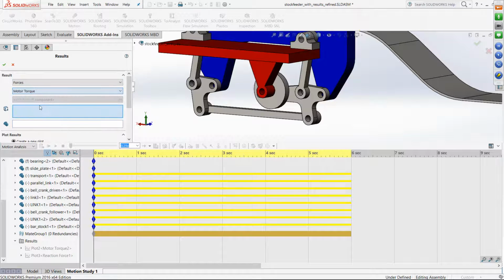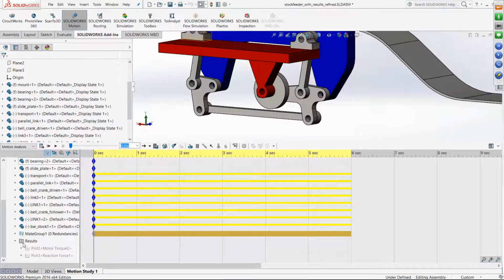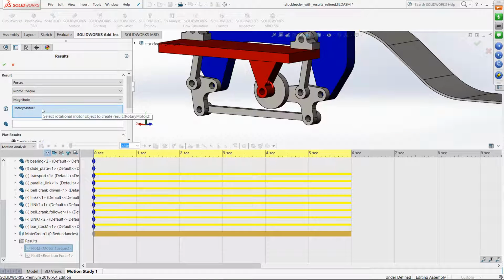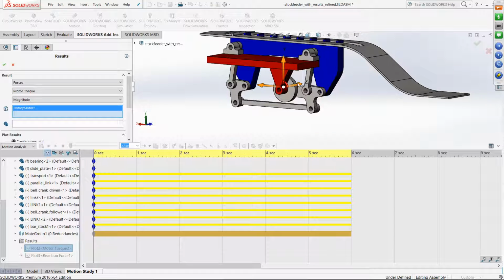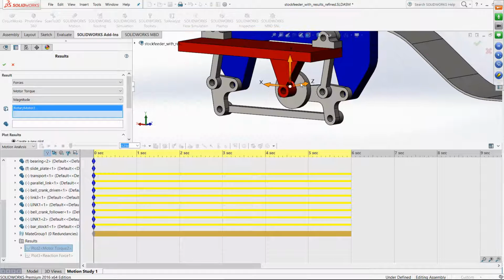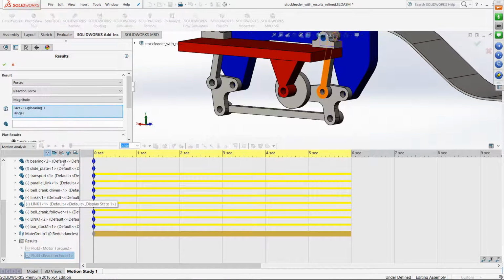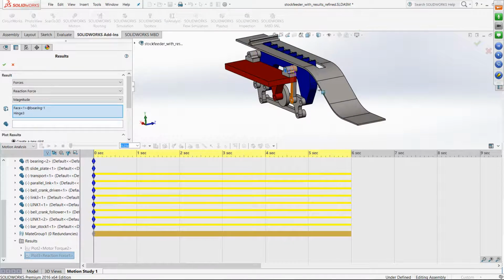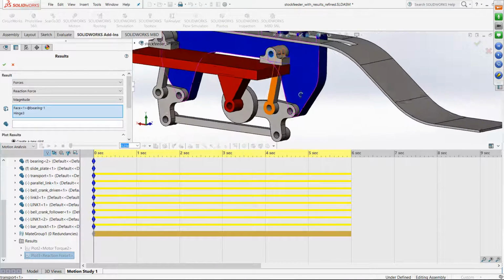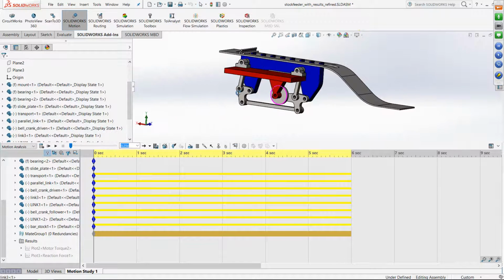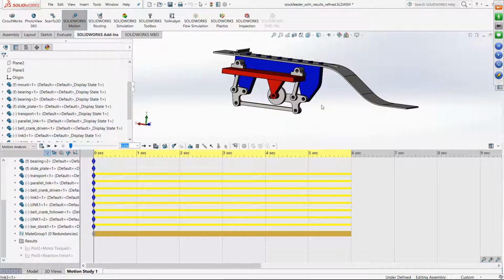I can select the motor torque, etc. So as I told you, this is not an animation software wherein we are actually just seeing the animations, but I can know the torque that is going to act on this particular object. So one part would be that, as well as you can find out the forces acting in different limbs. This could be further taken to stress analysis, and you can do the stress analysis to visualize and understand the forces which are coming in this setup.